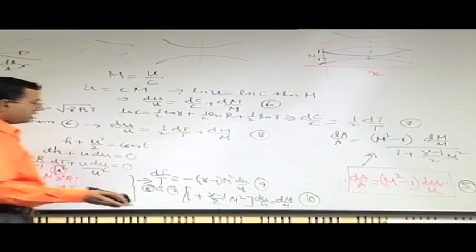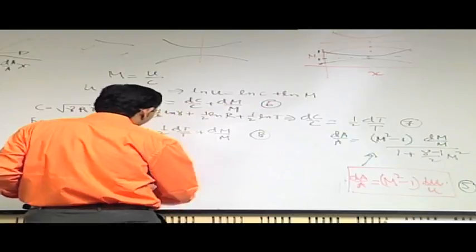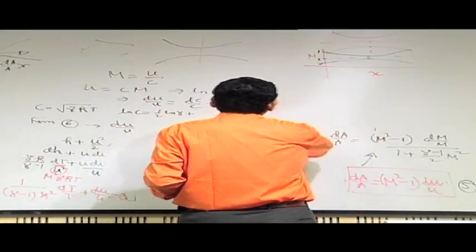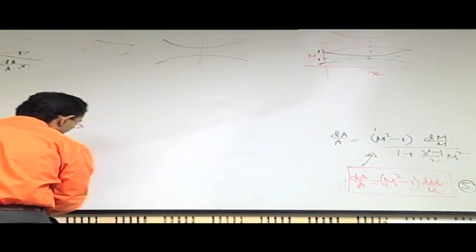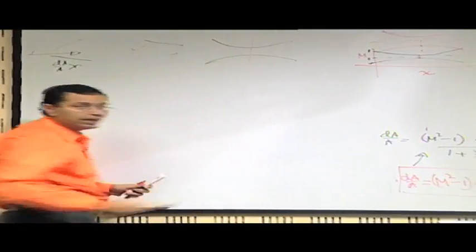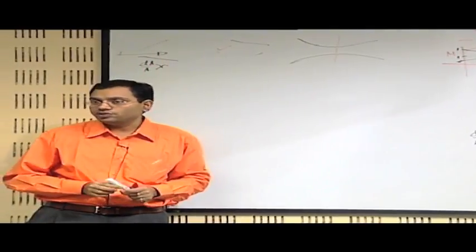Okay. Now, the other consideration regarding these types of flows is the achievement of a sonic condition. So, we have given some emphasis on that, and we have seen that if the sonic condition at all has to be achieved, that is achieved at a location where dA by A is equal to 0.